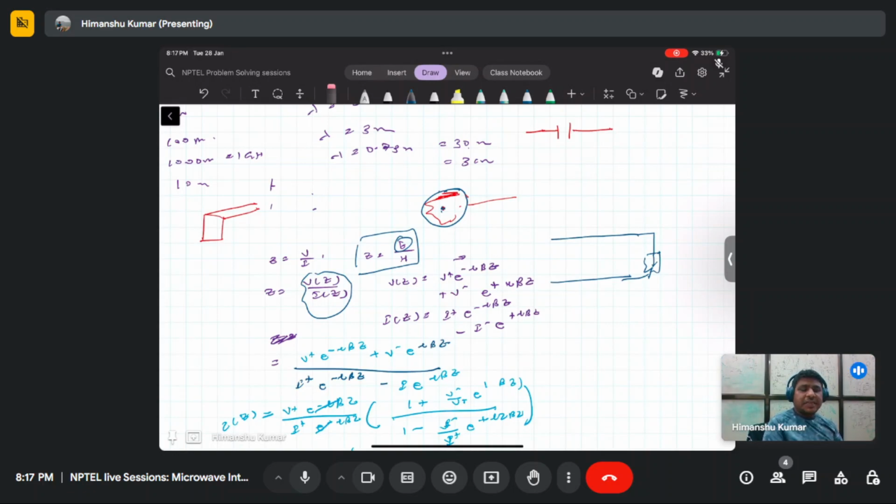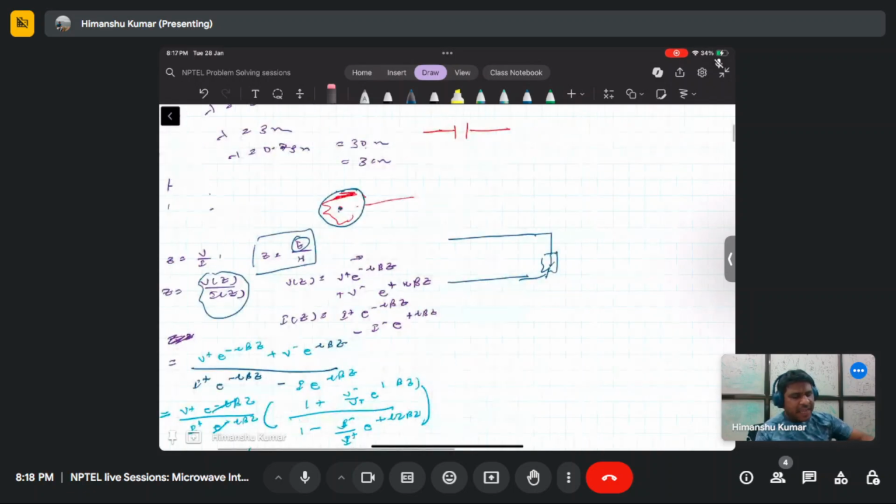So basically, that is related to the boundary condition. Even if you solve for other lines, such as the microstrip line, those have a very different boundary condition. In the microstrip line there is a ground plane, and on the top there is a dielectric. On the top you have the metal.